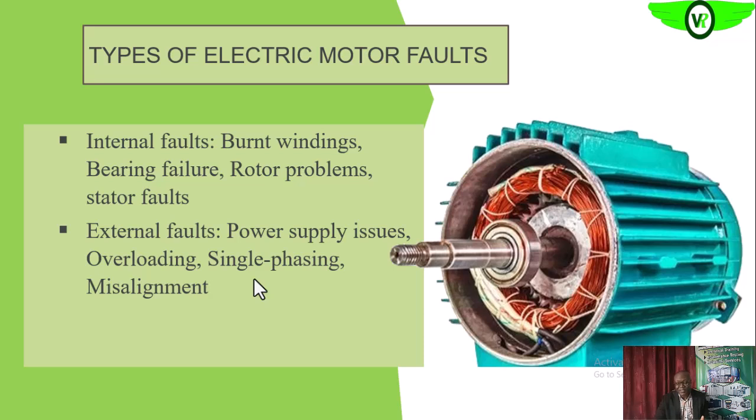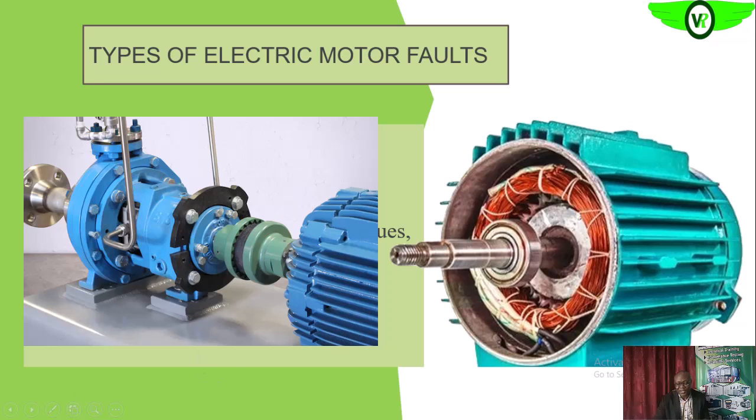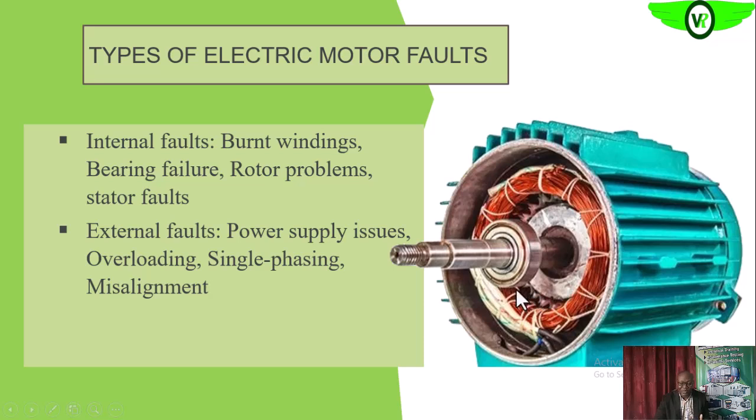And of course, misalignment will eventually transfer forces to the bearing. Those misalignment forces add up to the original or design load on the system, which will eventually result in overloading that can cause winding failure, or excessive load on the bearing that results in misalignment, which can also result in rubbing of the rotor, which can cause winding burn, as we'll see later.